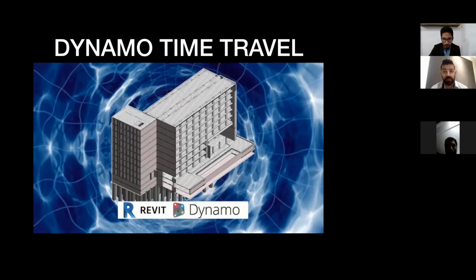So if in the BEP, that it's the BIM execution plan, you're supposed to work 17, but your company goes 19, you may use Dynamo as a pivot, so you can change elements from versions. Even Revit can do it. You can get the elements, get the complete data, and rewrite it on the new version, on the previous version or the forward version, whatever it suits better.